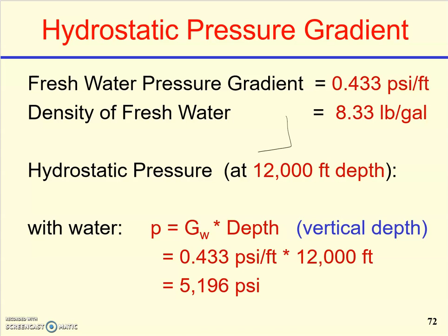So if you have basically a bucket of water, hydrostatic pressure means the pressure at the bottom based on the density of the fluid that you have. And the famous equation, rho g h, is basically talking about the hydrostatic pressure, and that depends on the density of the fluid, gravitational acceleration, and the height of the water, or the height at which you are calculating the hydrostatic pressure, right?